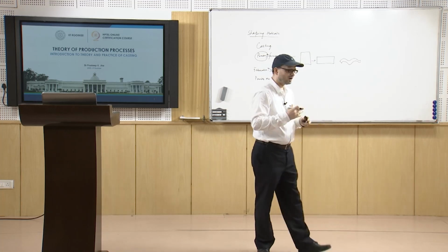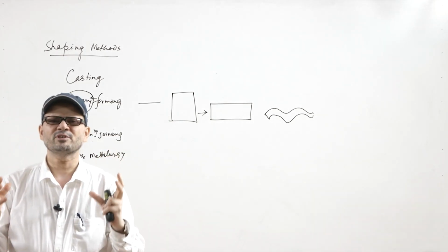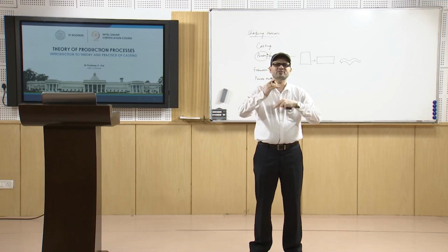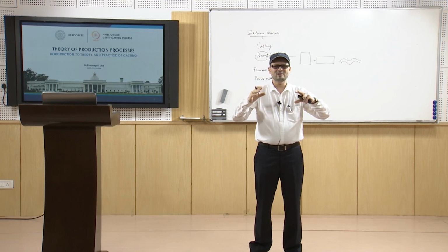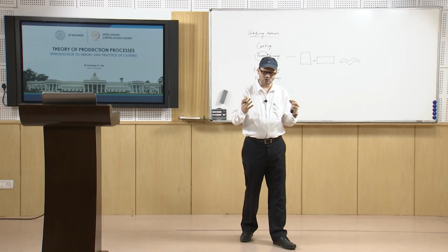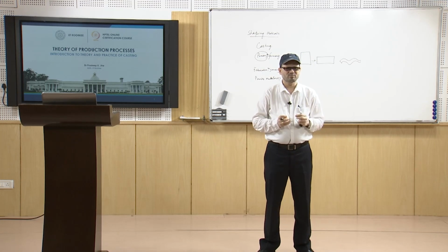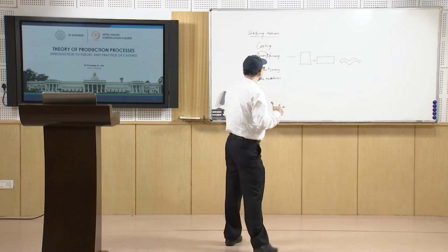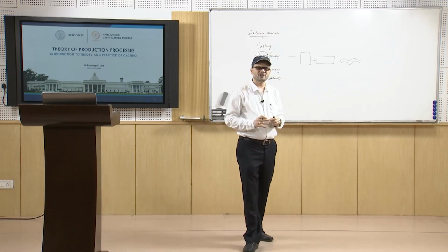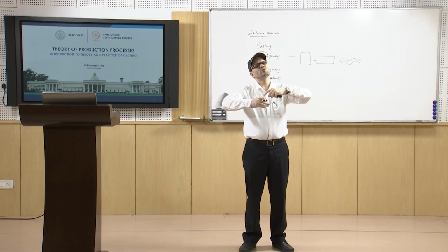All these properties. Now, in casting you are melting the material first. While melting, you have to see that the materials are normally of comparable melting points, and they should also have a gelling tendency with each other, they should mix with each other at the macrostructure level. Many times that is not possible. You may think of having a material with both metal as well as ceramics. That is not possible when you melt.